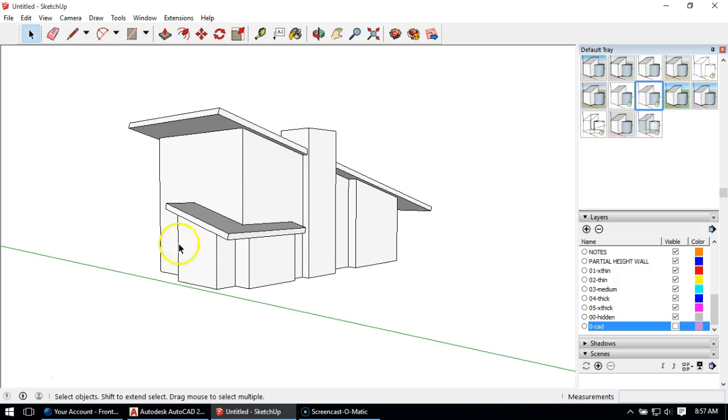So one of the things I had to do is I used intersect with model to knock out the upper parts of these walls. And once I did that, I had a hole in this segment that I had to fill back in, just by drawing the rest of the missing pieces of the wall. It wasn't too bad. I can help you if you really need to, but see if you can figure it out. And I deleted sort of the in-between lines. And I constructed both the interior side of this face and this exterior side of the face. I think that's sort of key to know.